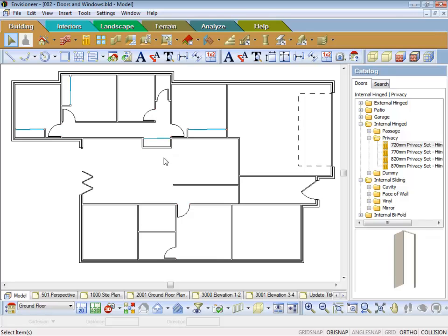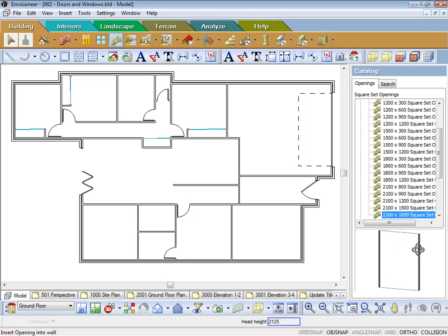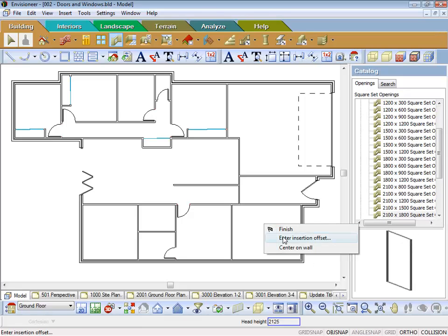Now what we might do is we might just cover some openings as well, because they're similar to doors. So if I go to an opening, let's say coming down the hallway here, we've got to put an opening through that wall there. We've got to put an opening into the living area here. So basically an opening, let's say I want a 2118 opening, because it's just a cut through the wall, and I want to center it in the wall, and that's all you have to do is just plop that in.